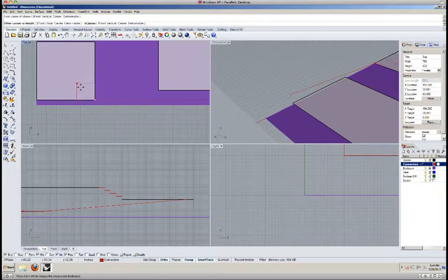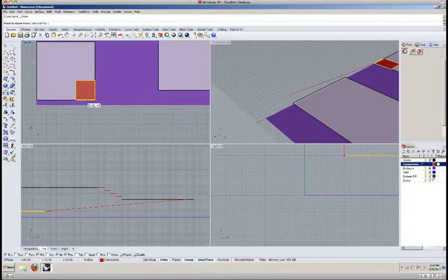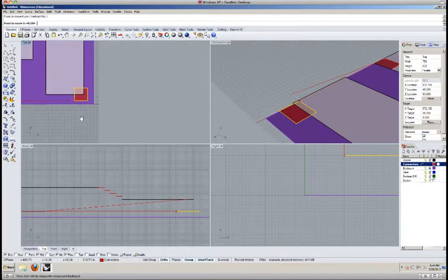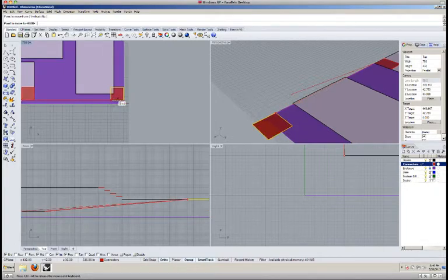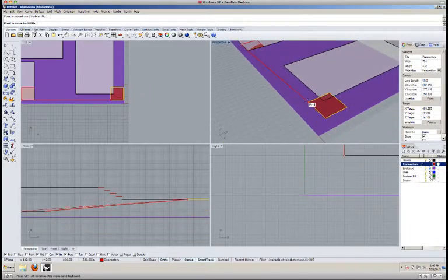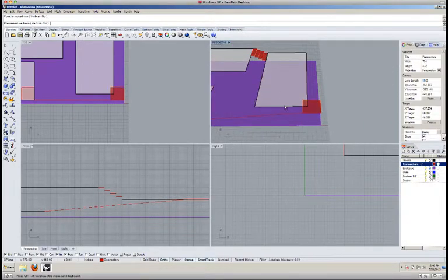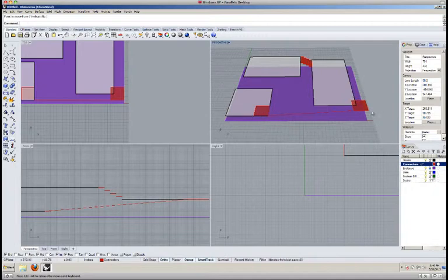So I'm going to box out a 4-foot by 4-foot landing. And I'm going to copy that from the beginning point to the end point. Because even if my line works diagonally between these two things, I'm just looking for the end of my ramp line. Here it is. Even if the diagonal line reaches, I still need to have 4 feet at the beginning and 4 feet at the end for somebody to get on the ramp and somebody to get off the ramp.